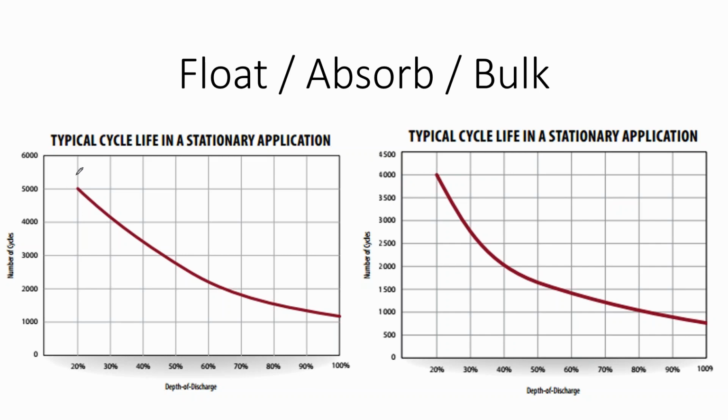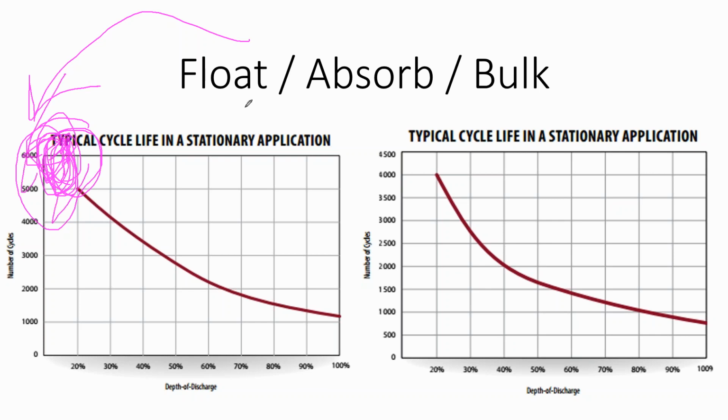And so what we're looking at is up here at the top, we're in the float range. And this is a very elastic range for the battery where it can float between, say, 48 and 60 volts. But like a rubber band that's stretched, you can't charge it all the way up to the very top before it wants to kind of drop back down in voltage again.